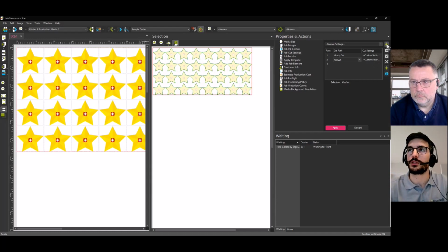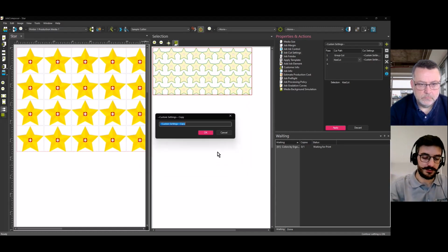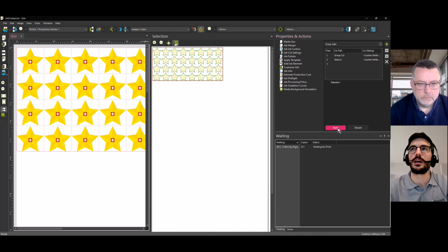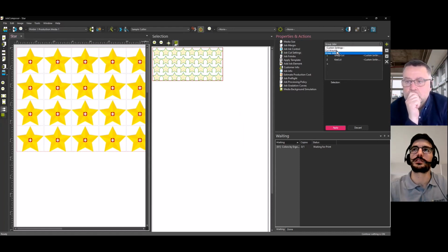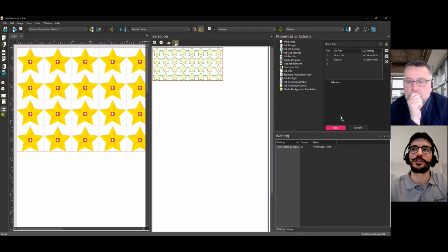So the thing that you're going to do now, I just go here to new, and I will save this group of paths, right? And I will save them, and call it group jobs, for example. So I know that anytime that I'm going to do this kind of job, I don't need to set this anymore. And I just come here to the settings and select, in this case, from cut around as this one and the group jobs. So I can easily change on my workflow on the fly.